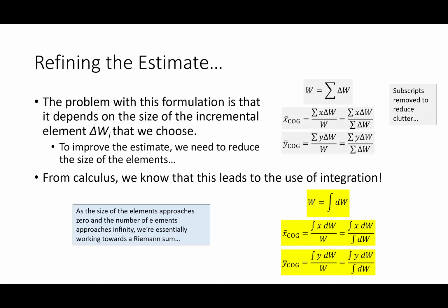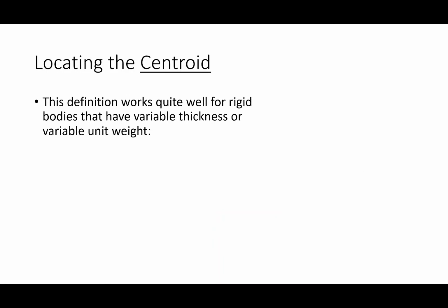Now, that's good, great, grand, and wonderful, but that doesn't get us to a centroid. Let me tell you the difference between a center of gravity and a centroid. The term center of gravity works very well for systems that have variable unit weights or variable thicknesses. As an example, it would not make sense to ask where the centroid is for a Honda Civic.